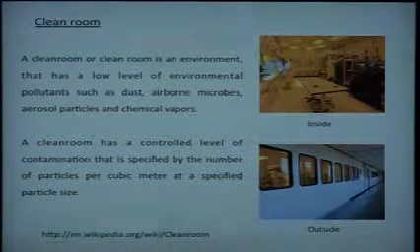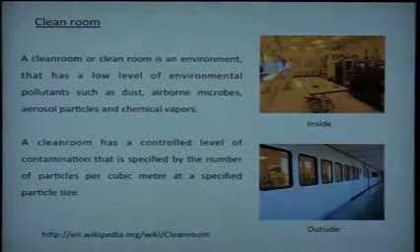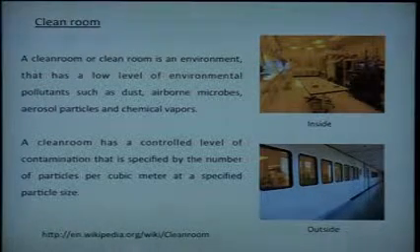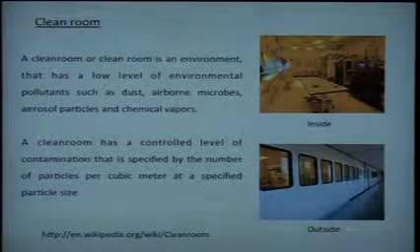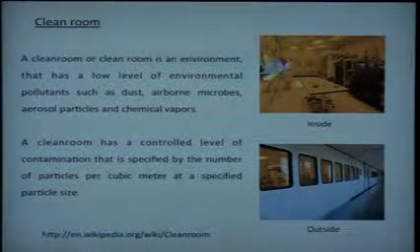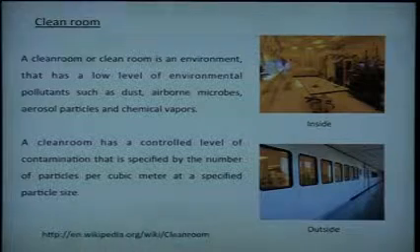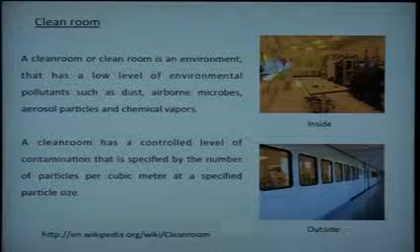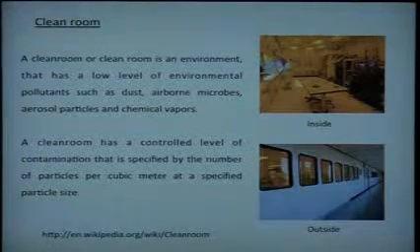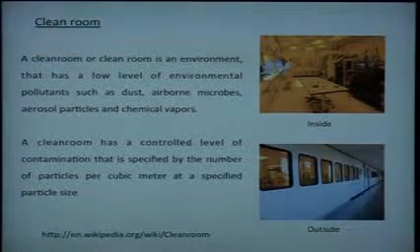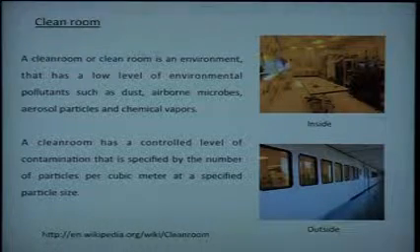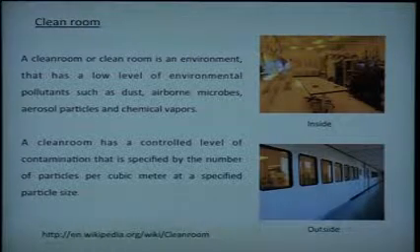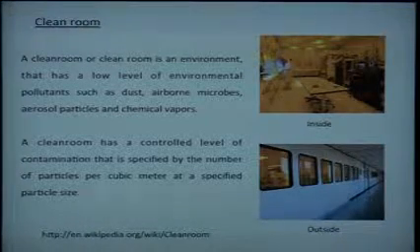So they can be devoid of, at least as a source of, collection of dust. So the specialty flooring and everything around there is made of something wherein dust accumulation is prevented, avoided, including the layers, including the clothing they wear. All that is anti-electrostatic. Okay, so charge is driven away, and typically it's all with yellow light, because the kind of photoresist and electron beam resist one would be using are sensitive to the other wavelengths in the visible region. So yellow is considered safe, and so most clean rooms operate with yellow light.